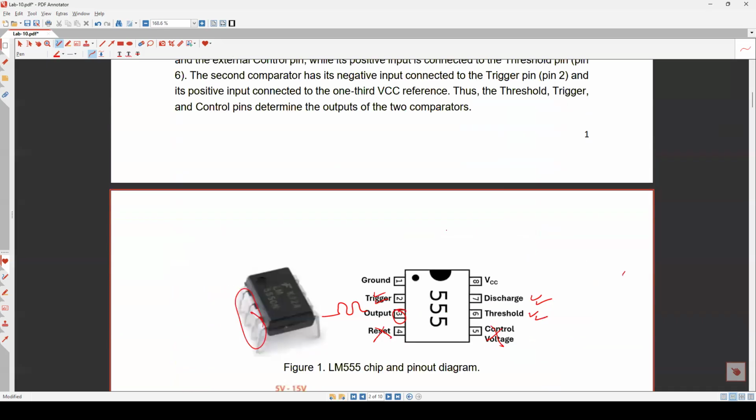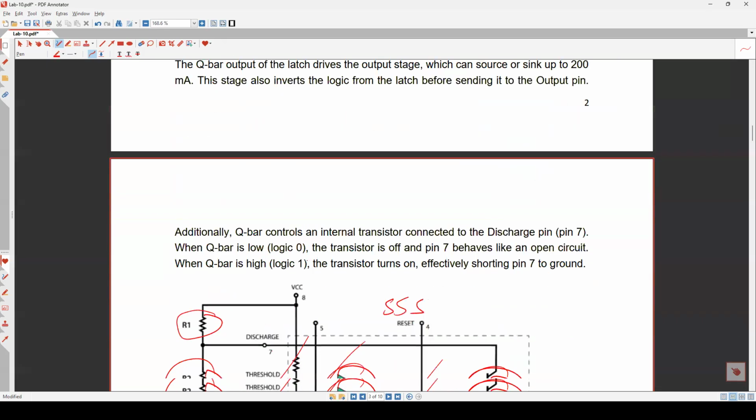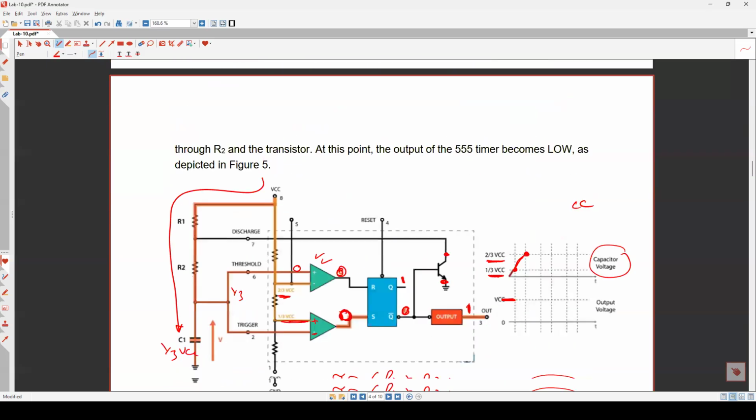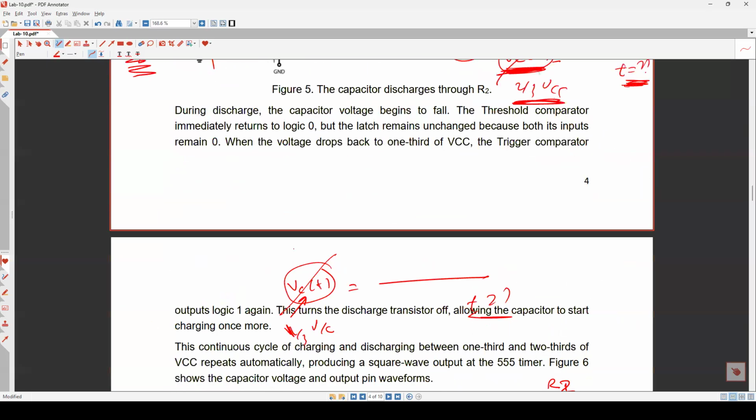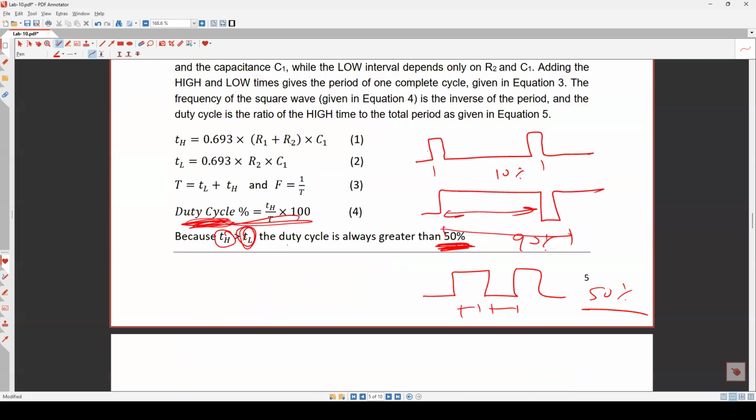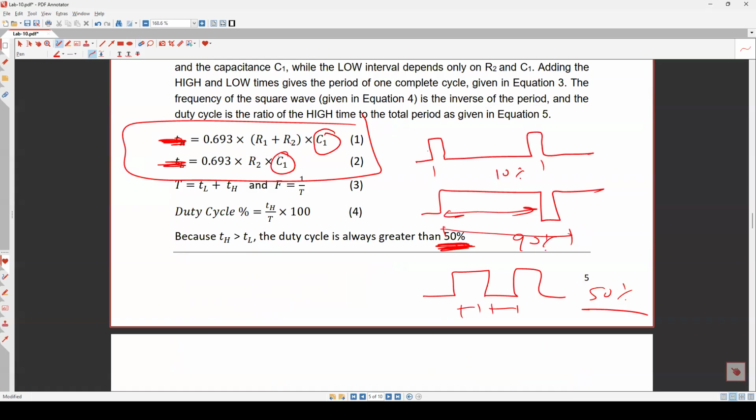Look here. The first thing you have to do in the pre-lab is decide the values based on the specification given to you, for example, whatever values you have for T low and T high. After that, you have to select a proper value for C first. My advice is to start with C, because usually we don't have much flexibility with capacitors. We don't have many capacitors, I guess. Also, making series or parallel capacitors may be a little bit harder. So first decide C, it's up to you.